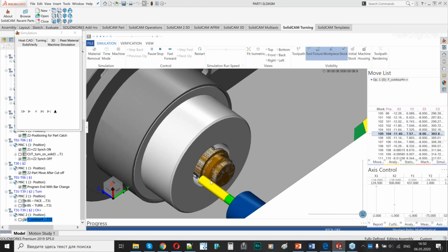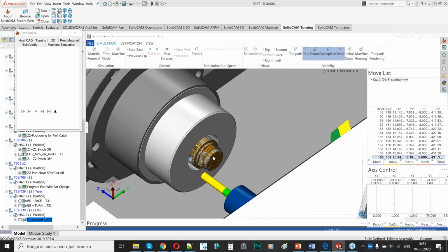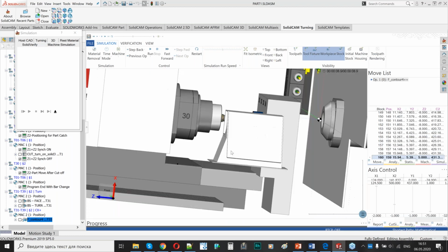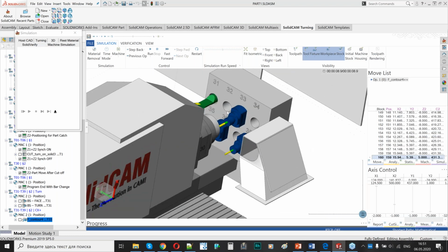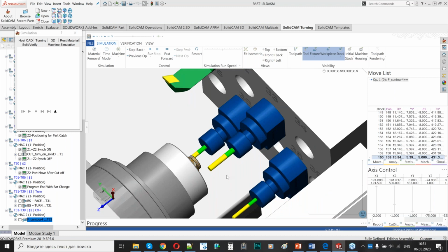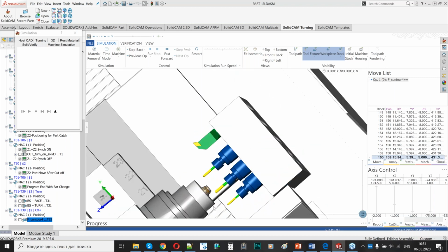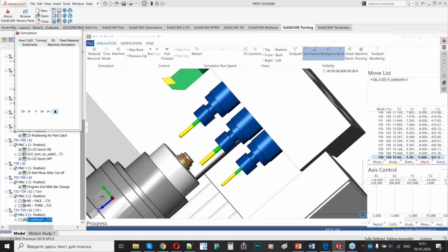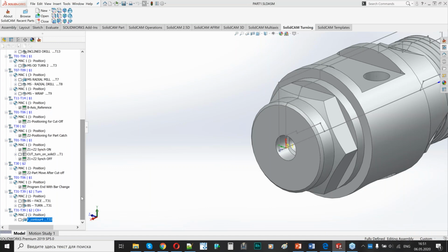So the tool will not move, we will have only C and X movement performed with the back spindle. But as you can see, this tool block is very interesting. It's not so common. And why can't we apply the cutting from the other side and perform the cutting with X minus? We can do this, and I will show how we can do this for this operation and not build a new operation. For this purpose, we have a separate type of combination.